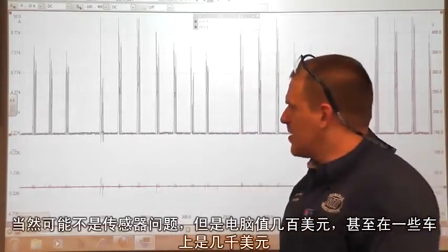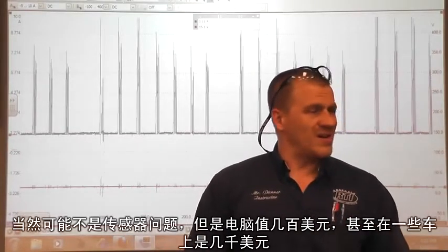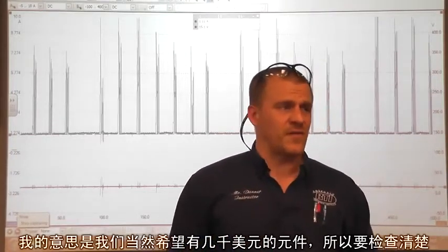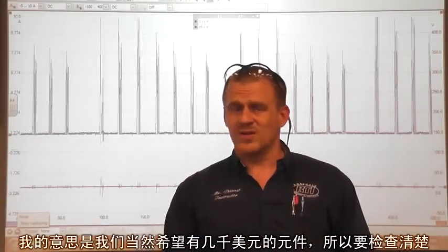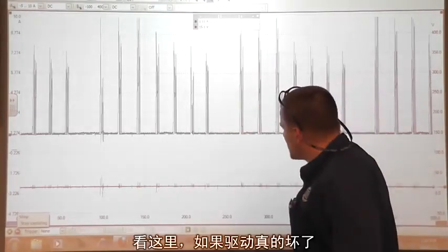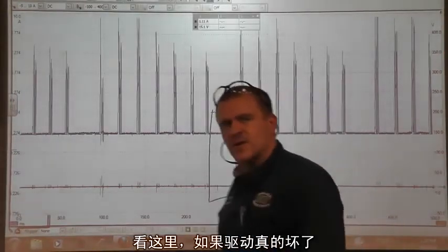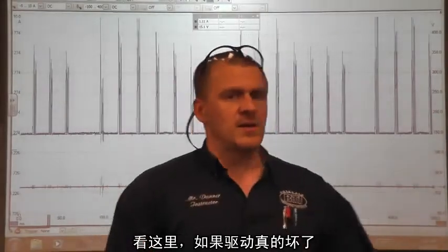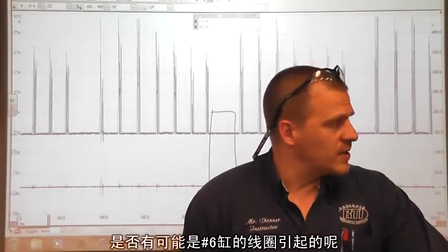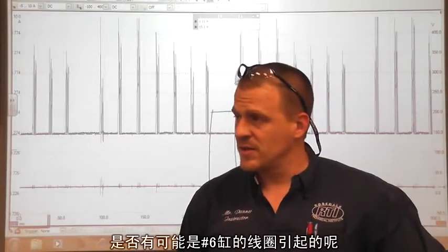Chances are that's not going to be the case here, but when it comes to a few $100 computer, some of these cars, maybe it's $1,000. I mean, we really want to be $1,000 confident that this thing needs a computer. So we're going to check those variables. One other thing to consider is this circuit right here. If this driver, in fact, did get damaged and got cooked, is it a possibility that cylinder number 6 ignition coil shorted out and caused this condition?